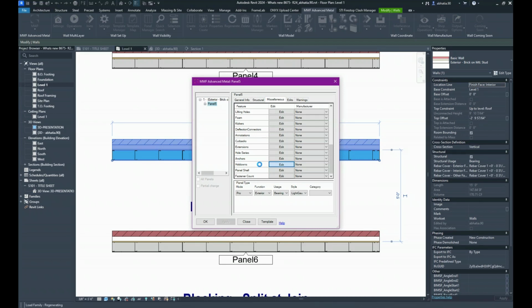But basically, we've given you a really cool option to add it to the hard side or open side of the member, instead of just giving you the option to place it on the start side or the end side. This way, if you have rotated studs, you can still have a hold down placed inside them. And also if you have any flip studs like I do here, and you might have a hold down placed on both sides, you can use this option for that as well. So just give it a quick minute to continue doing that.